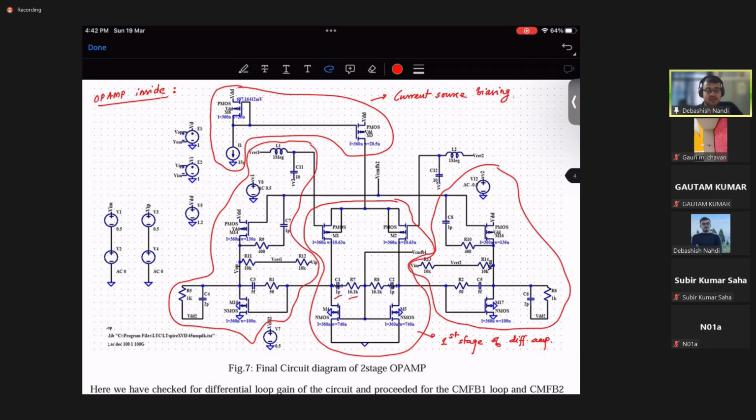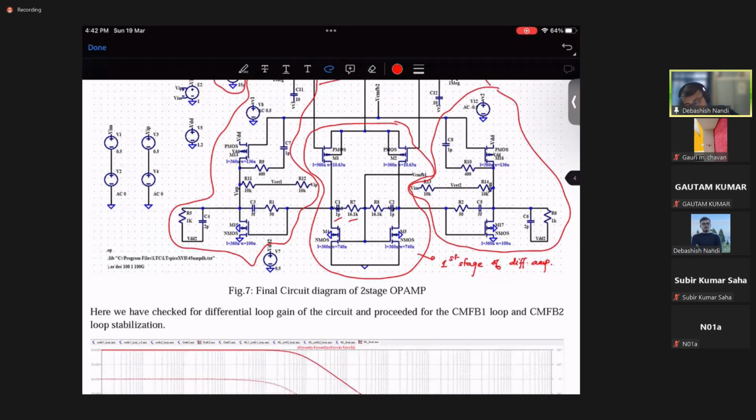And you can build upon stages, you can build upon third stage, fourth stage, but that introduces certain poles and zeros which degrade the circuit performance. But obviously you need to trade something off for other. The main purpose of this is, if you focus on this part, right? If you focus on the main first stage, you see that differential amplifier op amps are symmetrical, right?